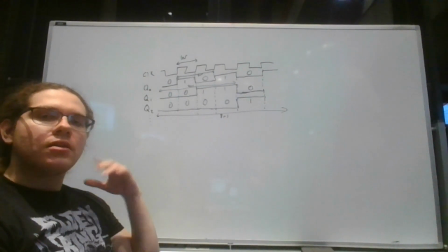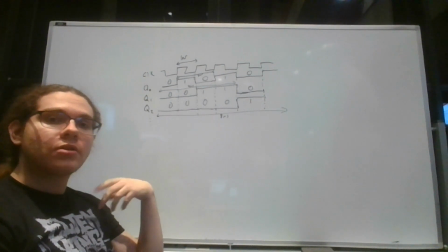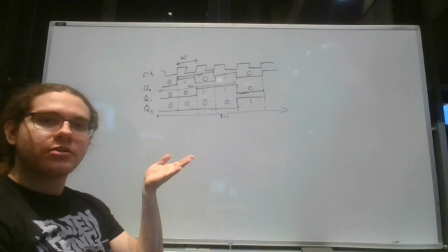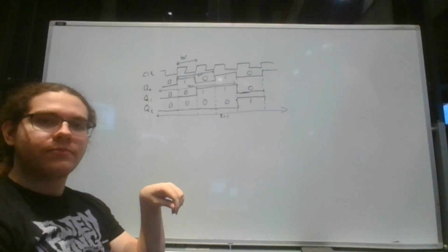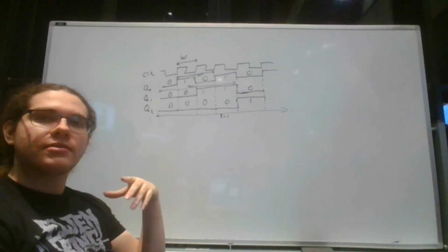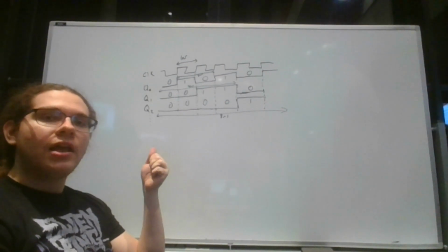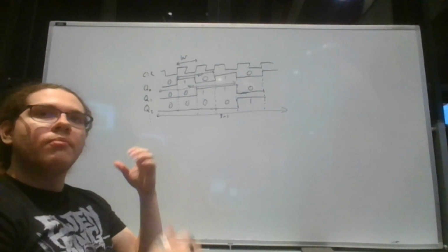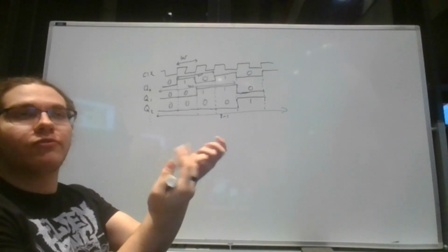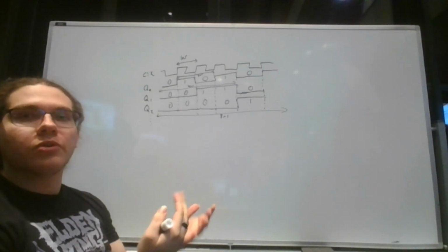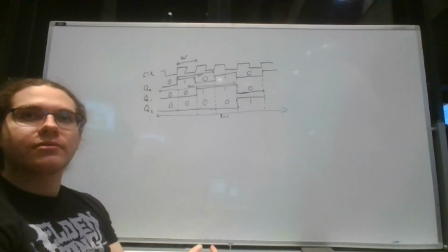The first is that you typically use the word register when you're thinking at a higher level of abstraction, whereas you use the word flip-flop at a lower level. The second is that if you have multiple flip-flops creating a multi-bit flip-flop, that's called a register because it's multiple bits.